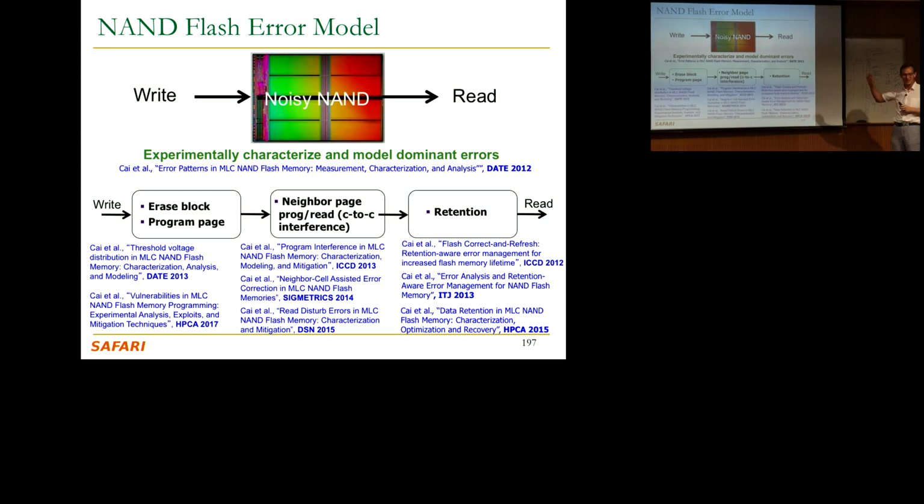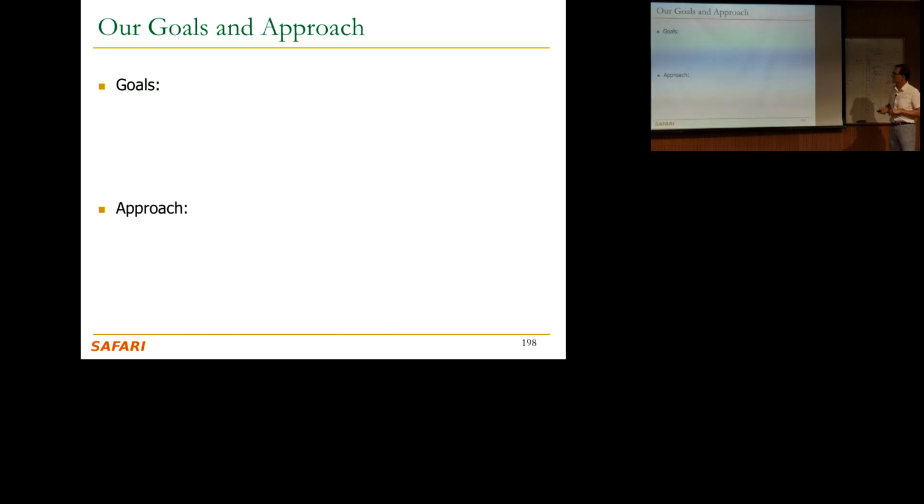Page and block, I'm going to get to that, yes. Actually, block is much larger. Page is much smaller, yes. And you erase at the block granularity because it's much cheaper to do so in Flash. You could erase at the page granularity at very high cost, so no one uses that. OK. Yeah, and there are more papers that I'm going to talk about.